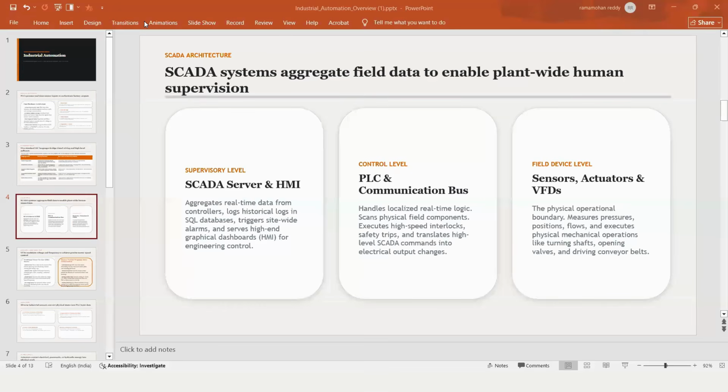And we have a few more options in the SCADA or HMI, where you can get to know which light is on and for what duration. You can take the data on what day and how much time this switch was on. You can also see the luminous intensity of that particular room and how many lights were on. If the luminous level is already reached, you don't need to turn on an extra light in that room. Suppose you have placed a luminous sensor.